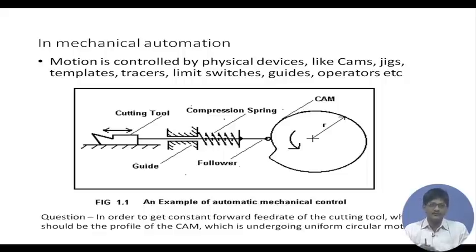Maybe it is moving forward, parting some job, and then again retracting very fast, the job is getting fed again. So, this continues unless something wears out, either the tool wears out or power goes off or the cam undergoes wear and tear. So, this is a perfect example of an automatic machine by mechanical controls. Okay.